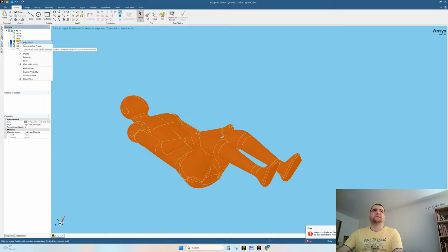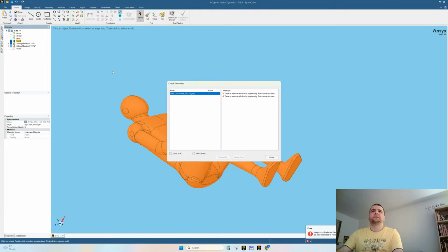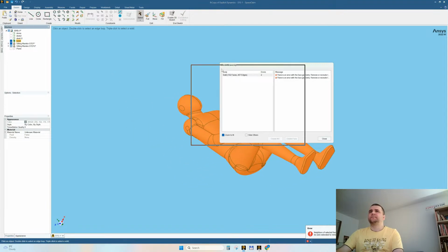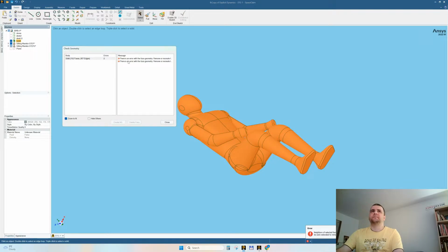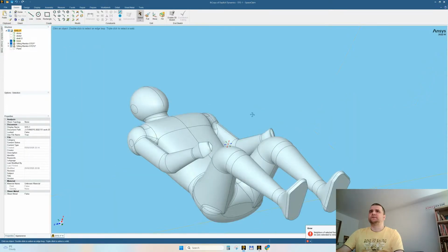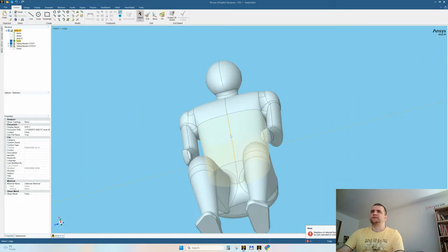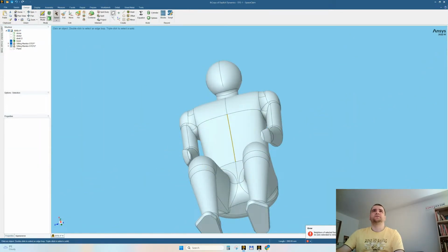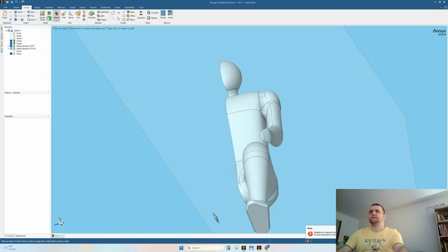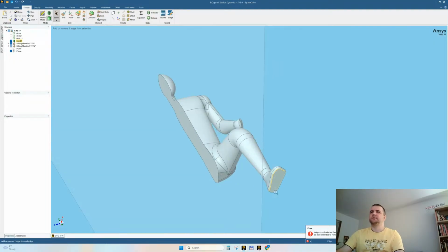If I right click, can I check geometry? Yeah. There is a problem. Okay. Why didn't you say so from the start? Let's select this edge, assign a plane, split body, this body with this plane. Let's delete this half, also this whatever, and mirror.